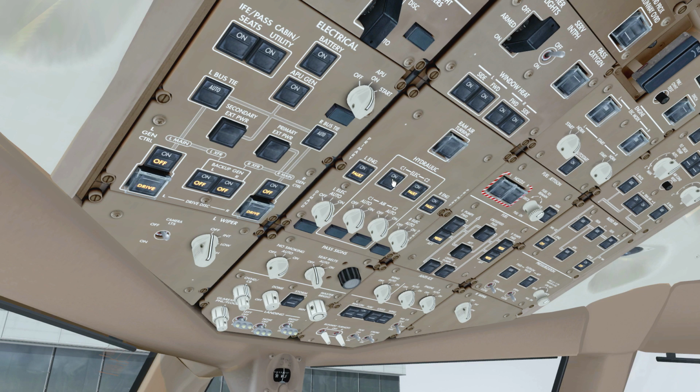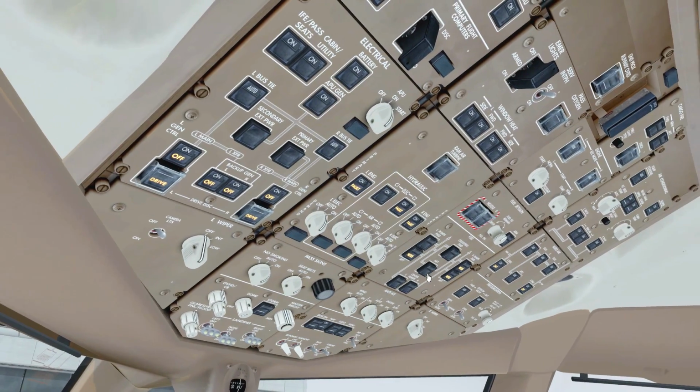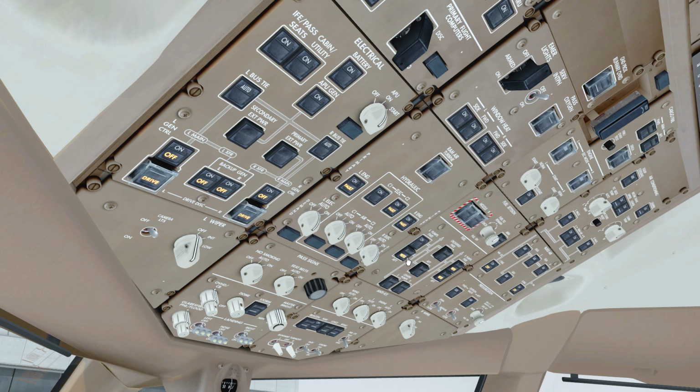The electrical system is supplying the two center hydraulic pumps, and the demand hydraulics are driven by electric pumps and two bleed air pumps. Okay, so demand hydraulics are only used when there's really a demand for certain hydraulic input. Then these demand hydraulic pumps will give extra pressure where necessary. And we can also start up all the fuel pumps.